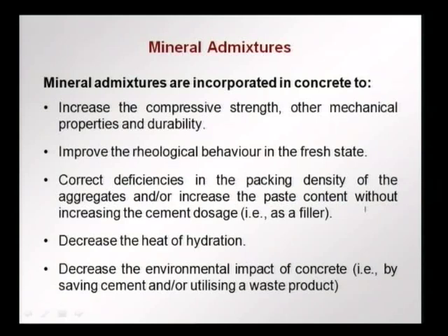Generally they increase the paste content because this is added on to the cement paste, without increasing the dosage. If you want to have a higher paste content, like in self compacting concrete, we need higher paste contents, so we need a filler material, and mineral admixtures are also used in those cases.